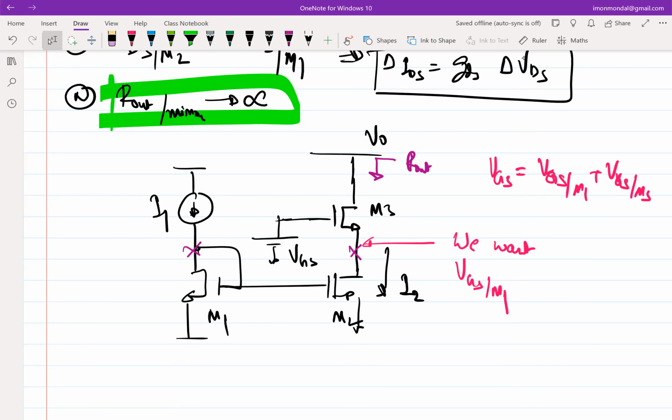So the corners in which it goes to higher threshold voltage, we call them slow corners, because threshold voltage is higher, so the transistor is probably slowing down. And in the corners where it has a lower threshold voltage, we call them fast corners. Threshold voltage is lower, the transistor probably has more capability of driving, right? So that is the terminology part of it, but the moot point is that when you are trying to design, you have to ensure that your circuit works across corners and across temperatures. Okay, so it's quite possible that your wafer came out at a slow corner and you are designed nominally for a 500 millivolt corner, and you have to ensure that across temperature also it works.